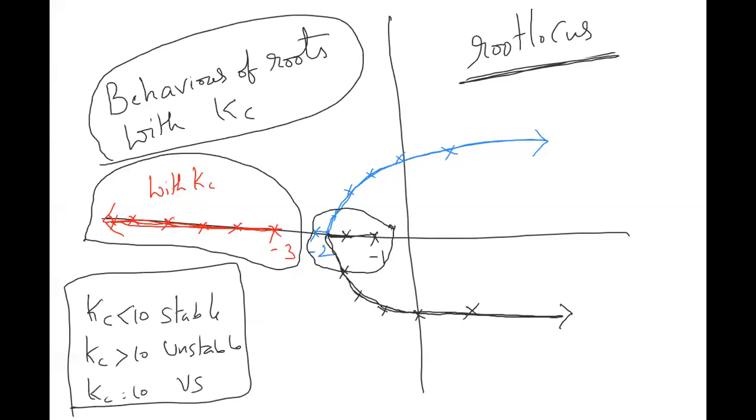Theoretically, in the plant, you should not go beyond 4.5 because this 10 has come from the models. Models may be inaccurate. Models have some loopholes. That is why I don't want to take a chance in the plant. Suppose in the CSTR, instead of opening, it closes the cooling water flow rate, then the entire reactor will explode. Then I need to shut down the plant for 4 or 5 months. Clear?